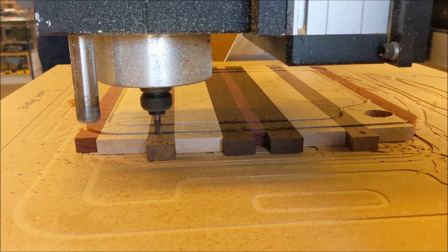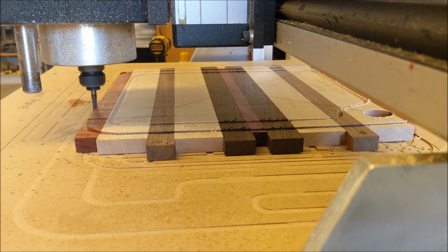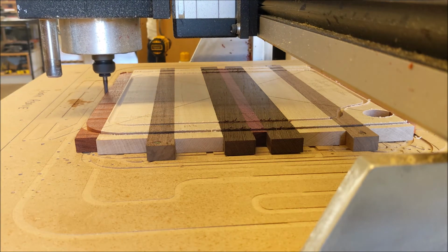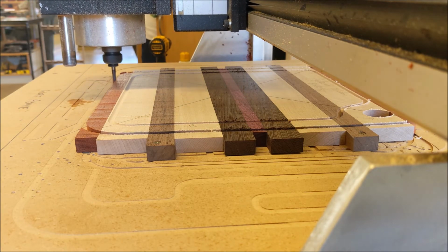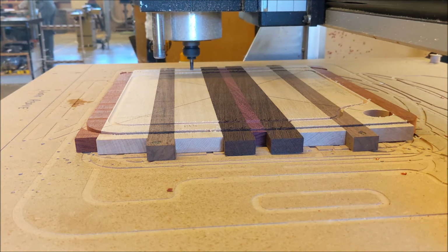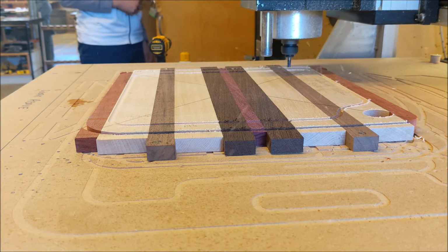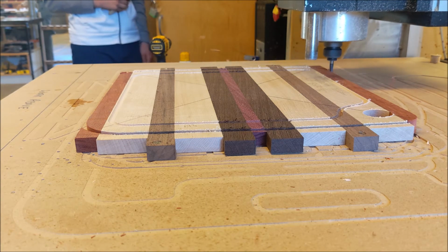And then, I don't know if you can watch this, it's really slight, but if you see that bit go up and down a little bit, let's see right there, you see how it bumped up and down? Those are tabs, and those little tabs are a way to hold the part down to the tabletop. So they leave a little bit of remaining wood left, and I'll go ahead and show you in the software